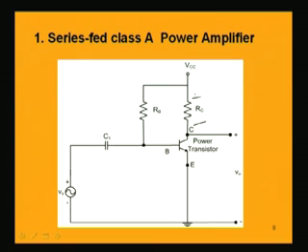A transformer is used to couple the output device to the amplifier. Instead of RC, we will have an inductive coil in the primary side, and the secondary side will have the load or the device which is connected. So, instead of this RC, we will have a transformer winding, and that will reduce the loss occurring by this resistance. So, that we will be discussing next.